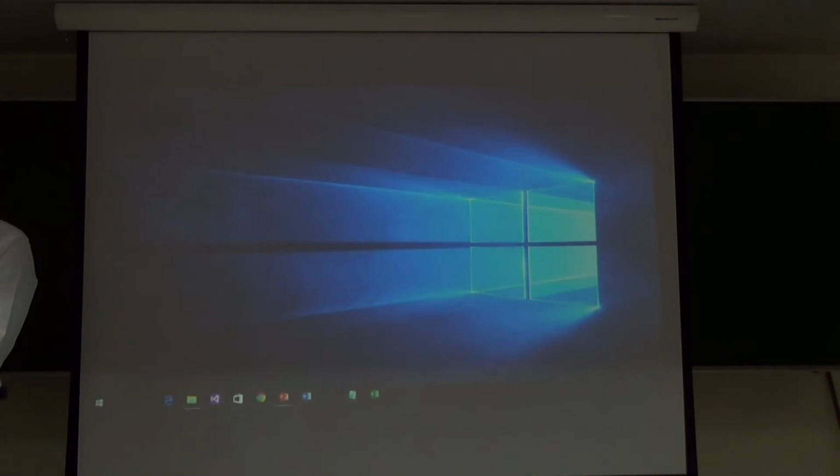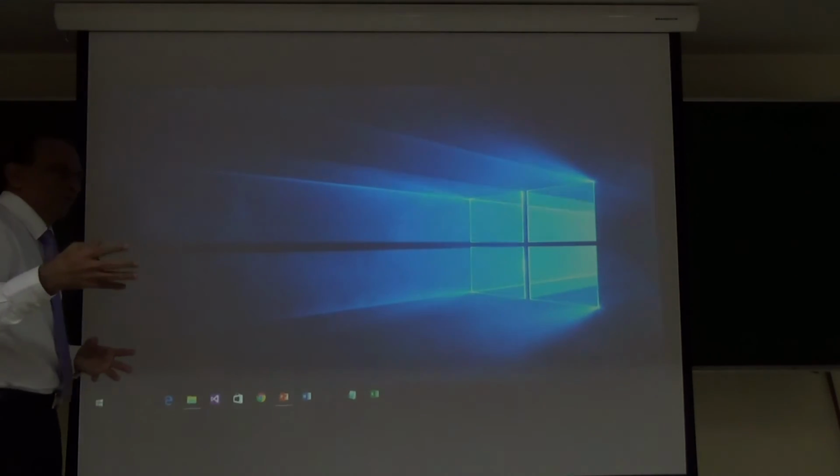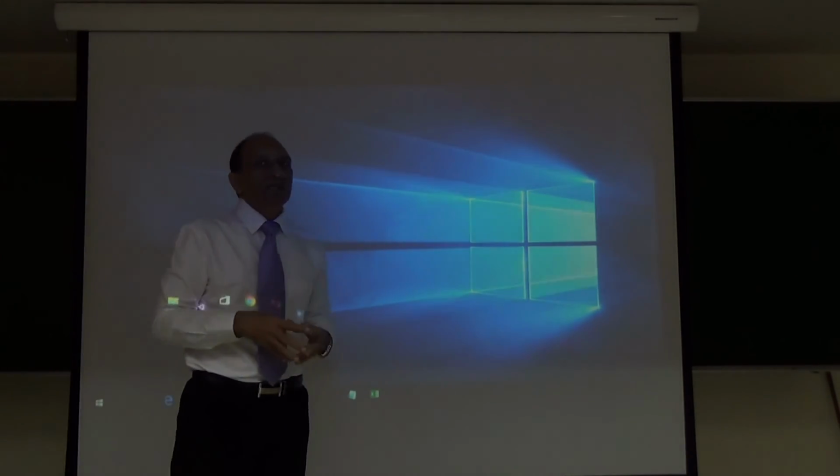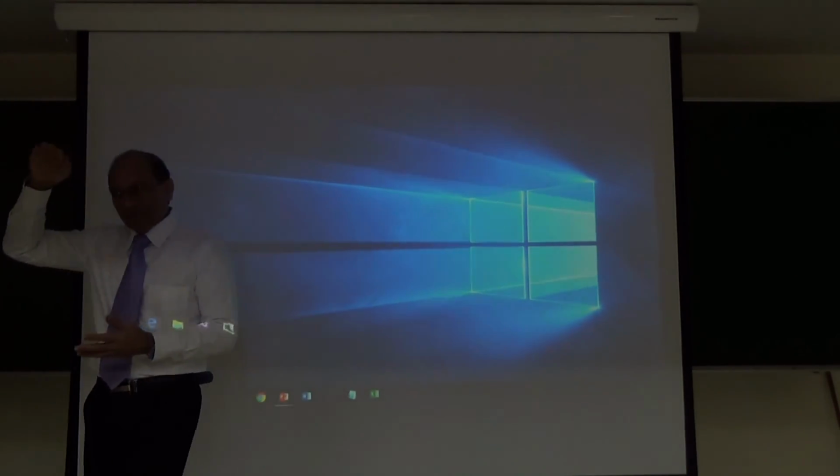Non-sway is related to one column, which does not sway and only bends, small delta. And the sway component is big delta, which is related to the sway of the building. Both of them have to be combined together to get the total moment magnification effect. And that magnified moment is then used to check the capacity of the section at each location.